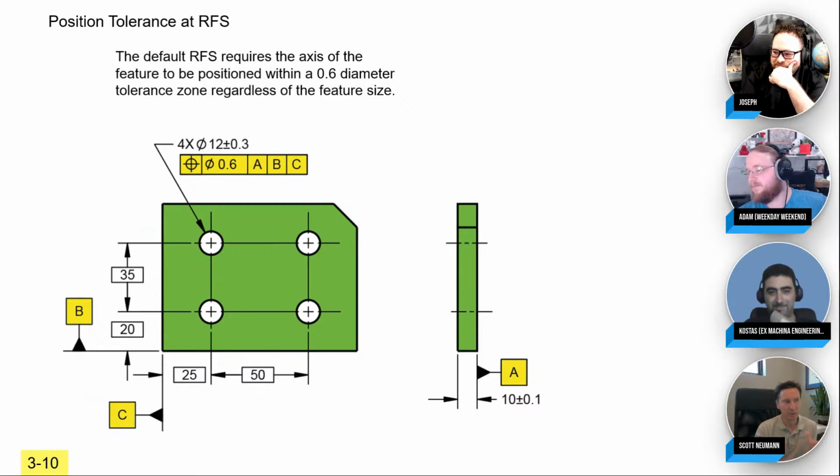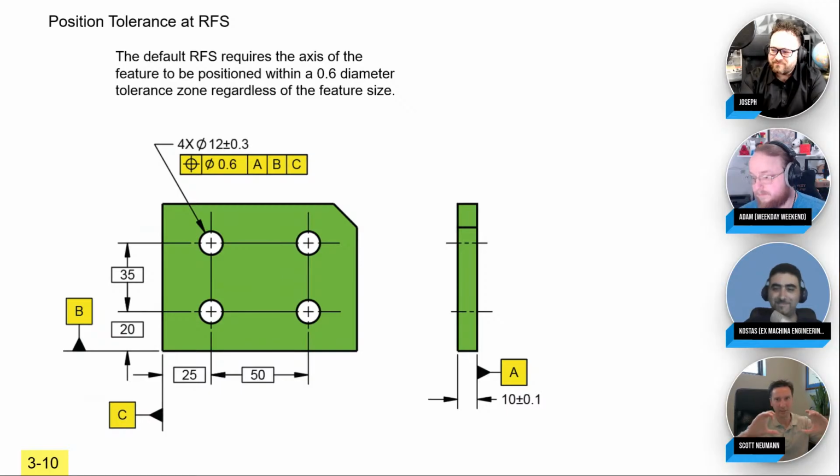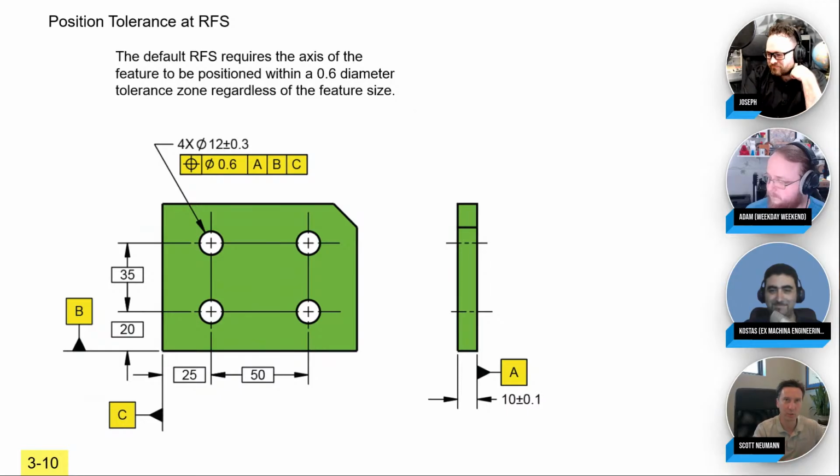And I think plus minus works really well for temperature and pressure and voltage. It's too much, too little. That's all you could ever have. When you have a 3-dimensional part with holes that can vary, perpendicularities and position tolerances in different directions, plus minus tolerancing didn't really work very well. So geometric tolerancing is a new tolerancing language for interchangeability on 3D variations.